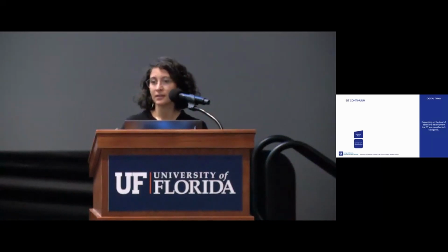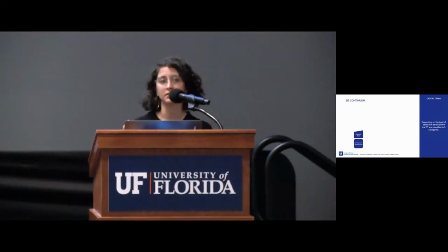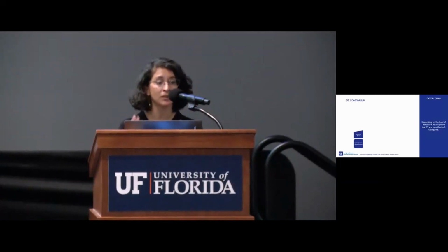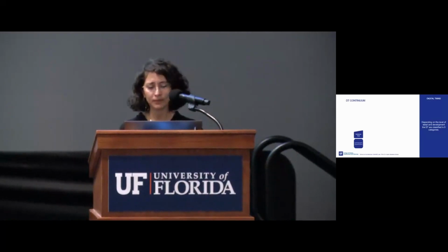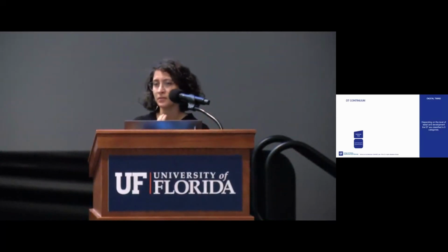One thing that I would like to point out now is that in order to create a digital twin, these different levels of detail don't need to be accomplished. So it means that you don't have to have a BIM model level 500 to then become a digital twin. This is something that you need to agree depending on the scale of the project. So if you have a project that is about the room, probably you do need to have a level 500. But if it is a project about environment, probably the level that you need will be around a 300 level of detail.